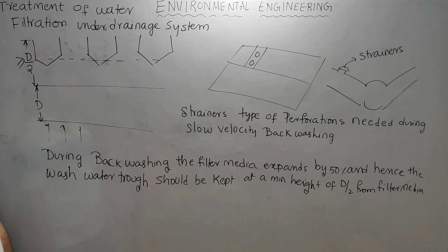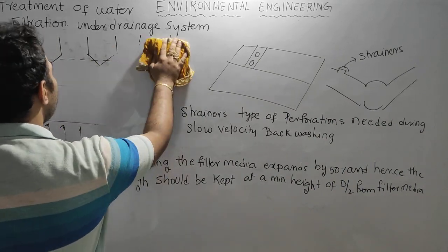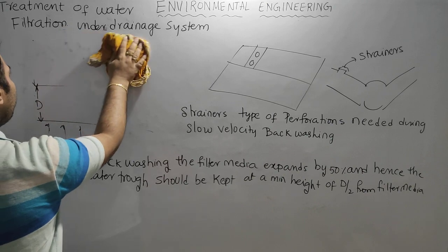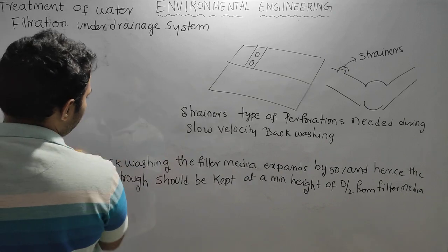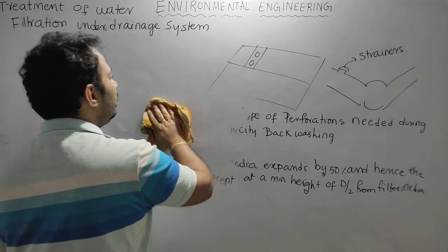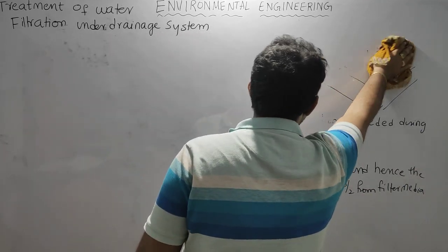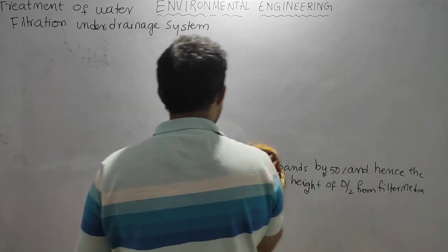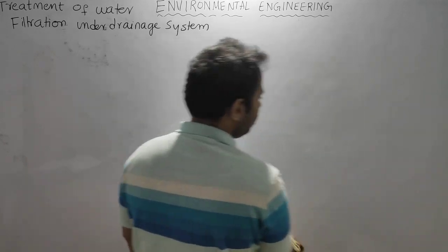And one more thing: how to find the length of the lateral, and also we need to check the safety of the lateral in terms of buckling, because the length of the lateral is very high and the width, which is the diameter of the lateral, is very small. That is why it may be prone to buckling. If the member is slender, then it is prone to buckling, so we need to design it safe for buckling.